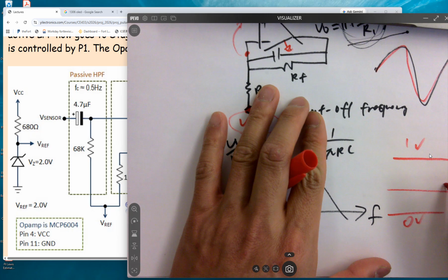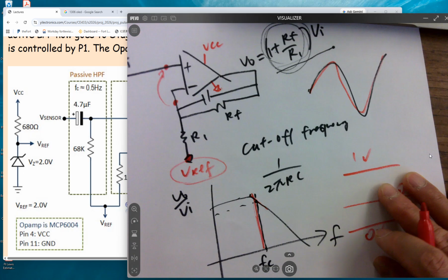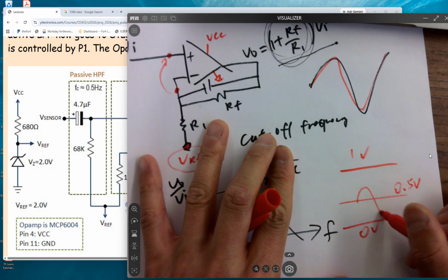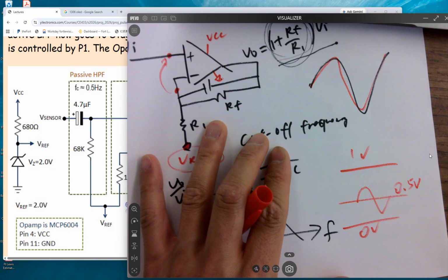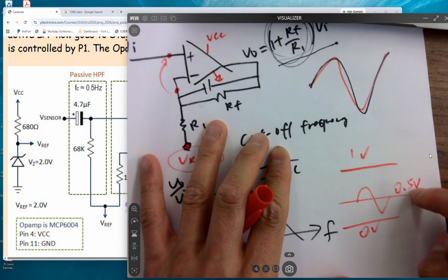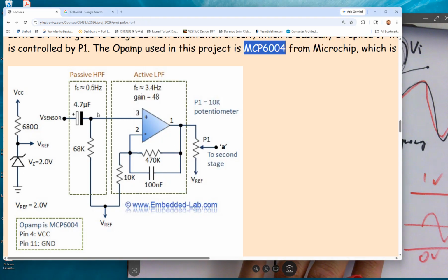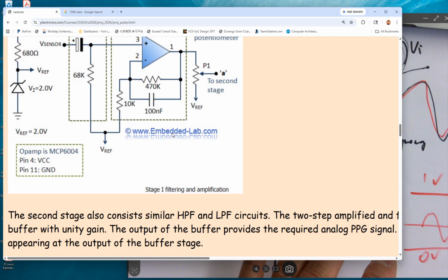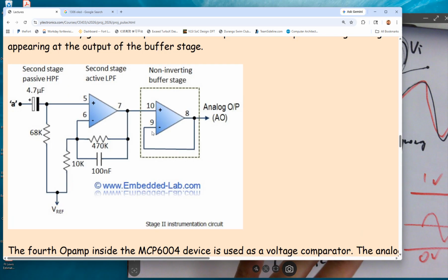So you want to lift your signal to 0.5 DC bias, and you swing your signal around 0.5. If you know your ADC is taking 0 to 1, right? So you want to use 0.5 as a DC bias. So your amplifier, your preamplifier, all the circuit here, the goal of building all these circuits is to give you a DC bias of 0.5 volts and an AC signal swing around 0.5 volts, but not exceeding 1 volt. So it's basically plus minus 0.5 volts swing.